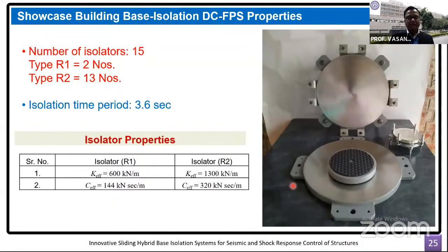During the Bhuj earthquake, the Bhuj hospital building collapsed, and there were fatalities. It was quite a sensitive matter because a hospital is supposed to remain functional during the earthquake and even post earthquake. There might be some increased inflow of patients, but that hospital itself collapsed. And when it was rebuilt with base isolation technology, it was to demonstrate that base isolation is essential for lifeline structures or lifeline buildings such as the Bhuj hospital.